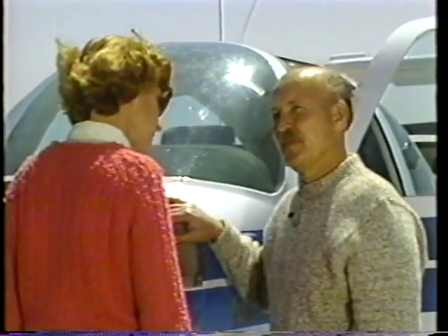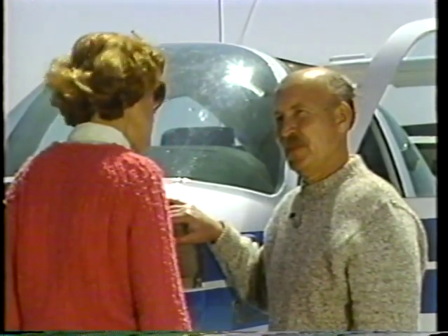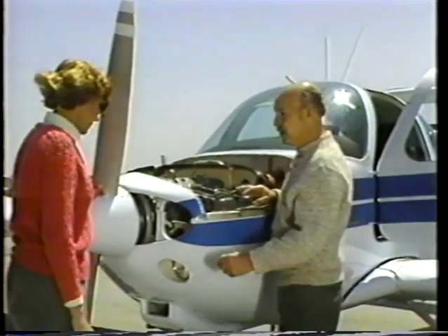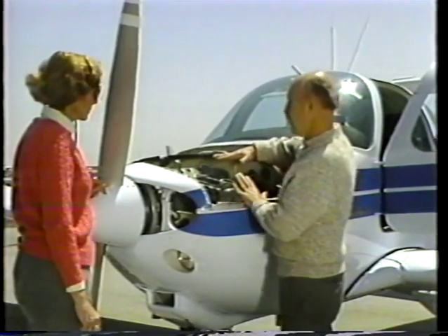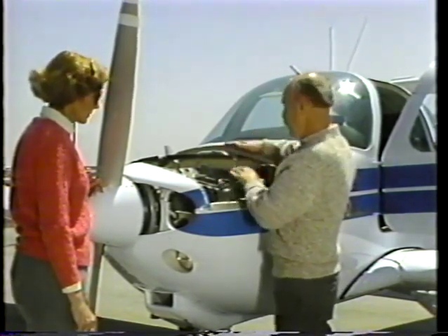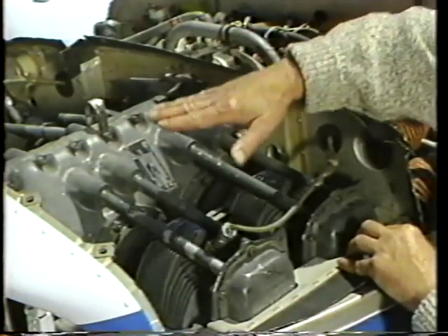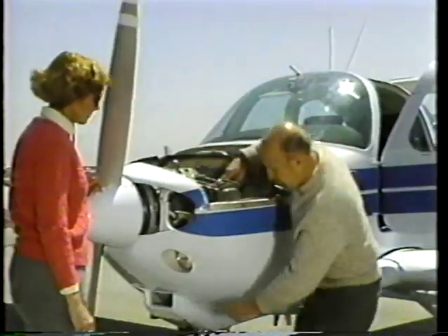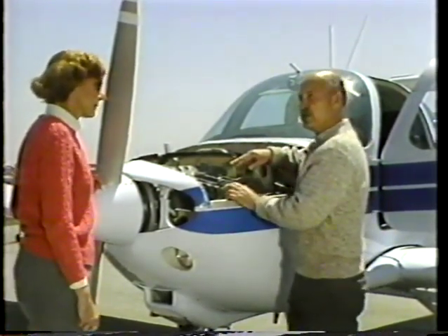Ken, with the tremendous heat energy that an aircraft engine develops, the cooling system is very important. Can you describe the Skipper's cooling system to us? Yes, Jeannie. The Skipper has an air-cooled engine, and the air enters through this port and the port on the other side. It enters into this chamber, and with the top and this baffling, it forms a high-pressure area here. The baffles keep the air from flowing out the back of this chamber. And the high-pressure air then is forced down through the cylinder fins. This carries away the heat, and it exits out the bottom. A great deal of the heat can also be carried away by the oil system.